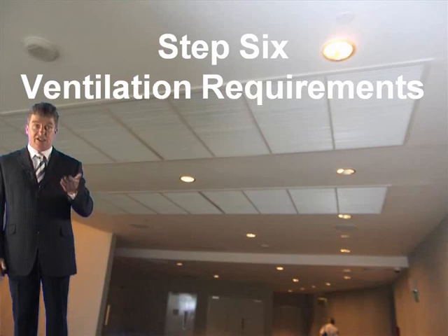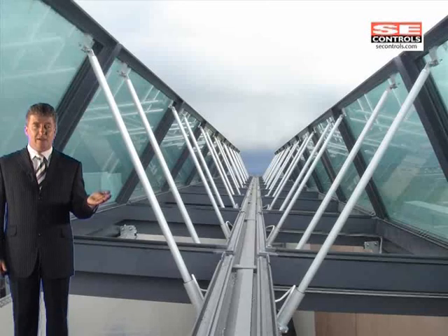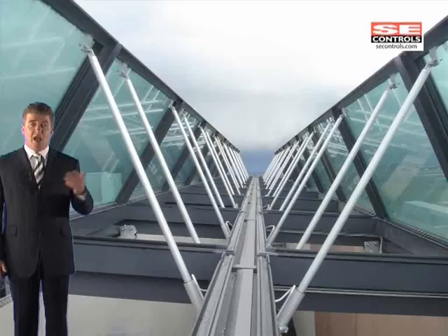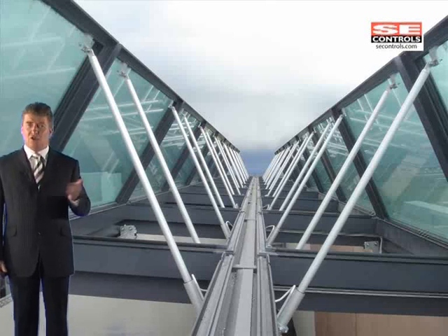Step 6, determining the ventilation requirements. Now you've got a couple of choices. You can either have natural ventilation or mechanical ventilation. And again, generally natural ventilation is preferred. Basically, a lot of it's on cost implications. But if it's not possible, if there's any issues why you can't have natural, then you might have to go for mechanical. So let's progress on the assumption that natural ventilation is going to be installed in this building.